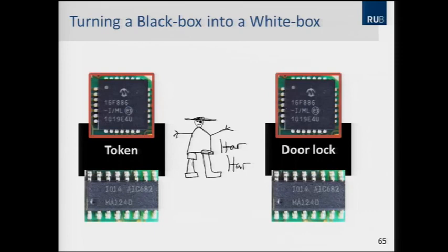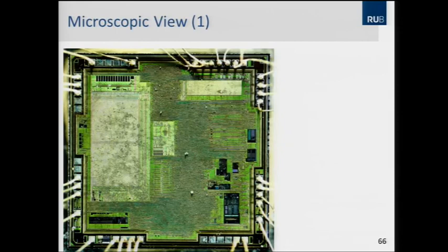This is a PIC microcontroller, and here we're fortunate that there are known attacks on these devices to extract the program code. Because these devices, what you have to know, have some configuration bits that can turn off the readout of the program code. And this was, of course, enabled, but we wanted to see what is inside the system. So we went to circumvent this, looked first at the chip, so you can find attacks for similar microcontrollers on the internet. And we found, okay, everything looks as you would expect on a PIC.